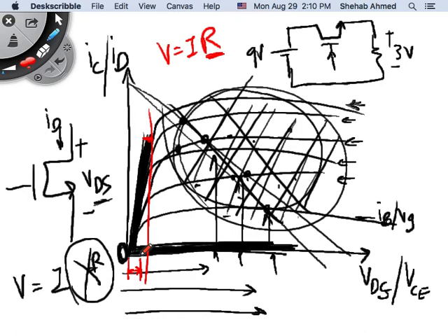Current passing through it is high. That's fine. Power is voltage times current. So my power across the device would be V times I. If the voltage is small, then the power loss in this device will be small. But in a linear regulator, I was putting 6 volts across here.